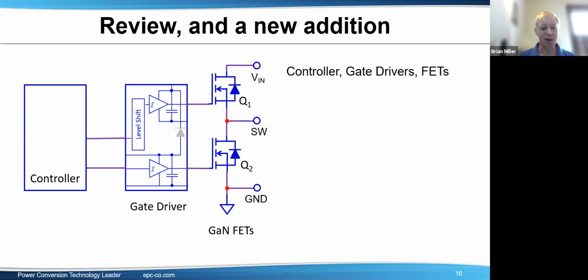The engineer I was talking to, I recommended just putting a resistor from the switch node down to ground to get some kind of loading to help. And that did seem to help to go through some debugging.